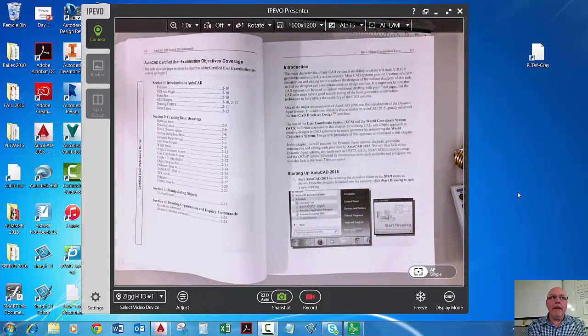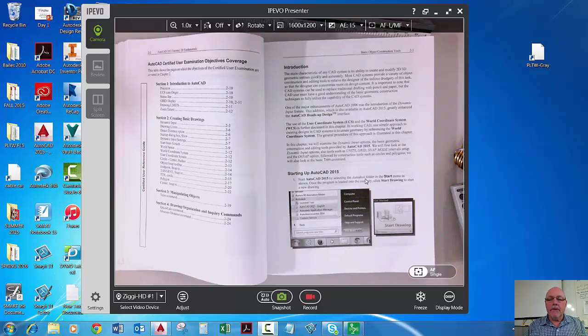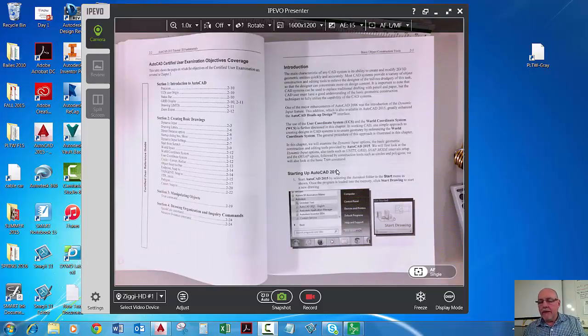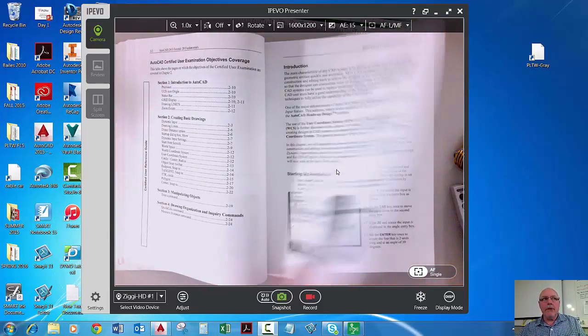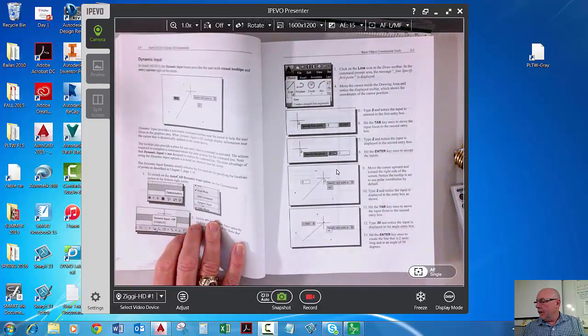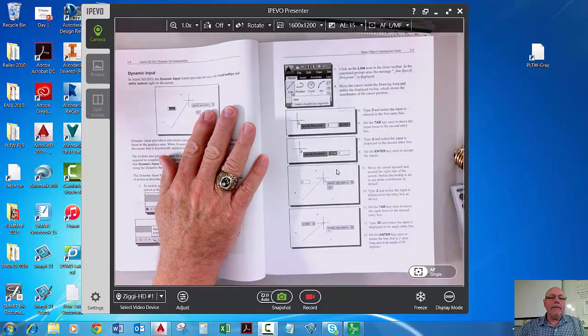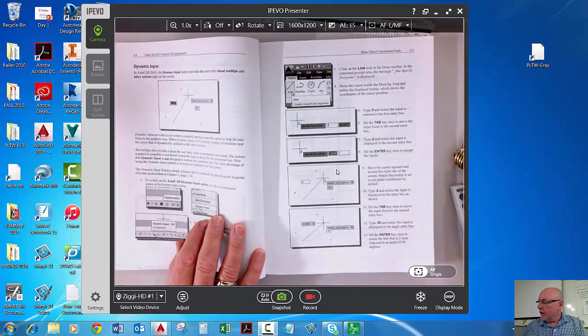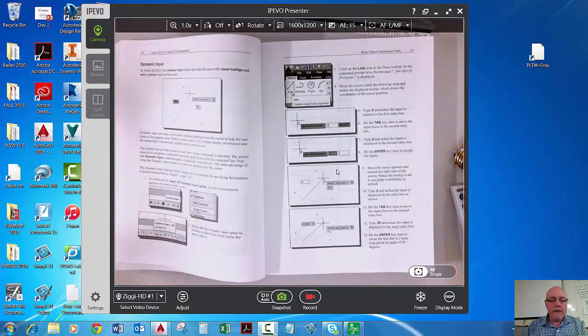So at the beginning, we're looking at doing the main setup of starting an AutoCAD drawing. So you'll go through and get your AutoCAD started. You'll see your startup dialog, that little snapshot of it shown there. Okay. Then we begin by looking at the dynamic input feature. Okay, and we go down here and we switch that on. Okay, so let's do that.